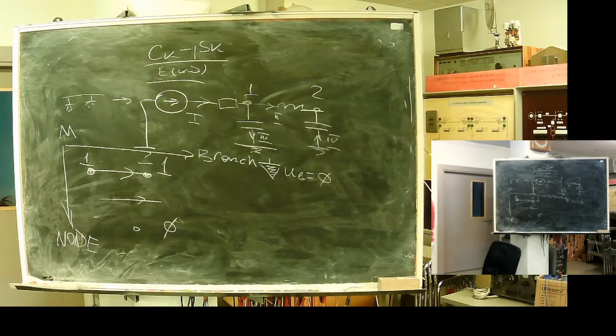What if it's a hanging branch? Then it's also 0, right? No, it has nodes. We have hanging node. Let's say network, and branch is hanging. We have a node at the end. We don't have current here, but we can measure a voltage. If we can measure a voltage, it's a node. In the next moment we can attach something, just extending the matrix. If nothing is attached, current is 0, but node exists and voltage can be measured. Maybe it's useless.